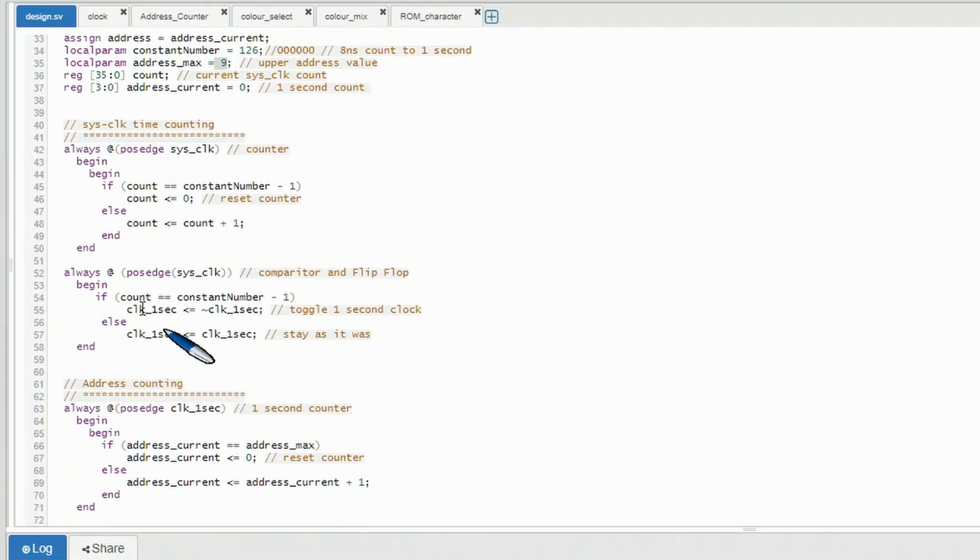So looking initially at the counting, I've broken it up this time into a couple of different detections, and this basically forces the synthesizer to more concisely create what I want. So this part will create me a flip-flop, and this part will create me a counter, whereas when I combine them together, the output may be a little bit more jumbled. So this helps keep it a little bit cleaner by, if you think of this as a discrete piece of electronics, it will separate the electronics.